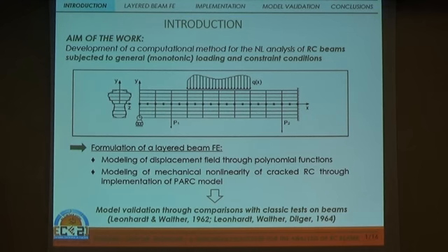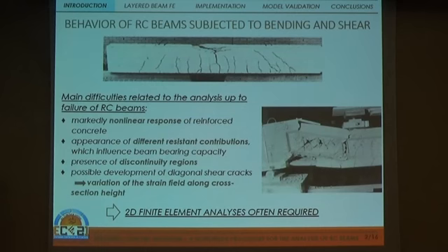the beam height. And further, this model allows to take into account the mechanical nonlinearity of cracked reinforced concrete through the implementation of a shear crack model to evaluate the stiffness matrix in each layer of the beam element. And the procedure is finally validated through comparison with results from literature.